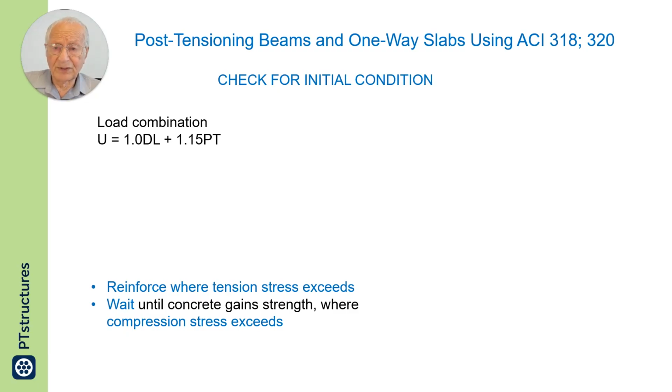After we do the shear design, we go to initial condition. Initial condition is evaluation of the member at jacking, at the time the post-tensioning is being applied.